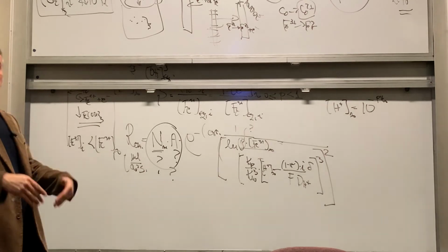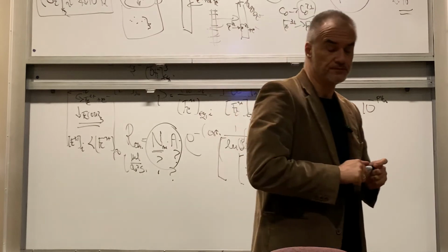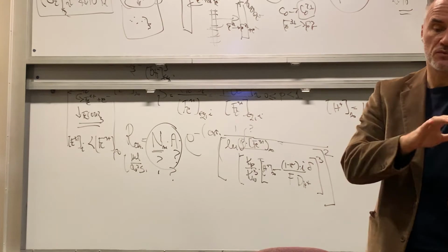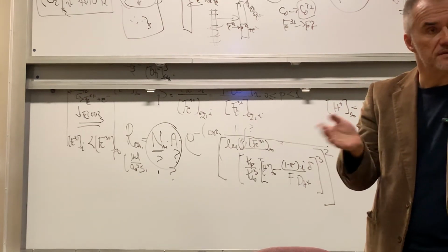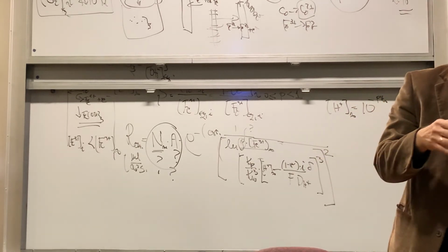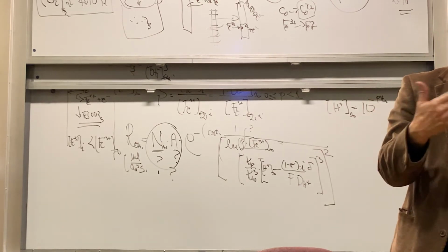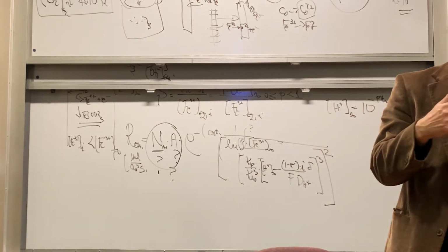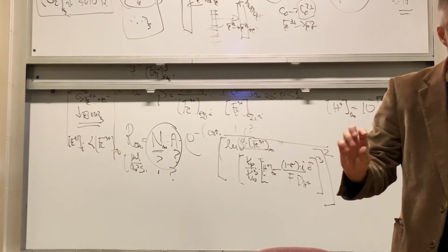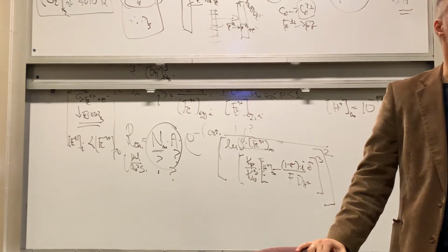Okay. Let's discuss what we can do with magnetic element. We can measure magnetic moment. Magnetic moment is a tricky measurement. When you measure magnetic moment, for example, using VSM, what you really do, you measure magnetization, and then you have to divide this magnetization by the volume of the film, and then you get B sub S, which is the saturation magnetic moment of the film, right? So you need to know accurate dimensions, meaning thickness and width, the volume of your film. That's number one.